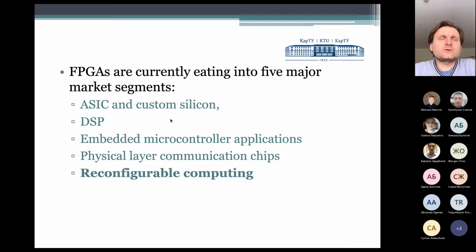So we may, in the same way, change the properties of our video signal. For example, when we cut off some frequencies, we introduce filtering of the noise. We may blend the background based on the behavior of the signal changing. Also, we may mix two signals. So using DSP technology, we also may introduce non-linear behavior of the signal. It's easy using the FPGA, and that structure may be changed during the design of the system. It's easy to connect our gates, our registers, in another way.